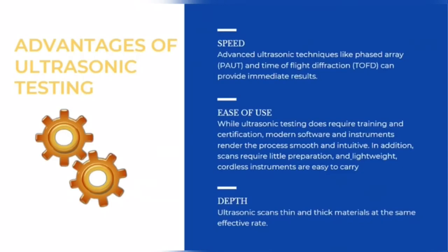Advantages of ultrasonic testing. First, in terms of speed, advanced ultrasonic techniques like phased array and time of flight diffraction can provide immediate results. As soon as the probe passes over the surface of the material, the instrument software displays a visual image of its interior.